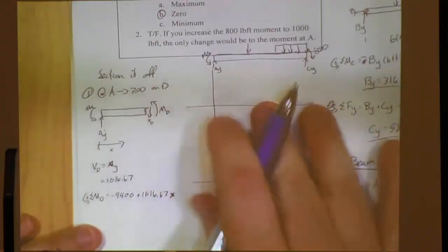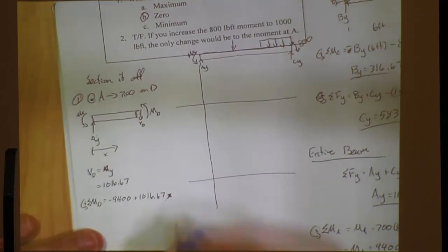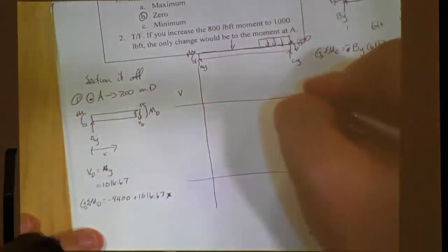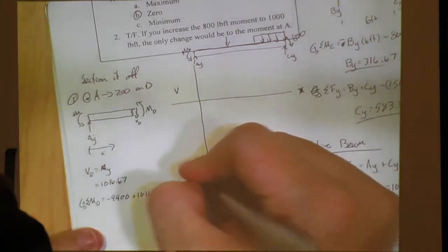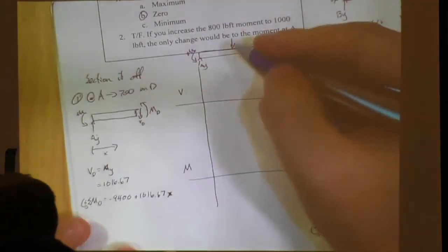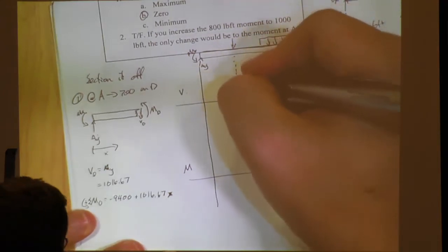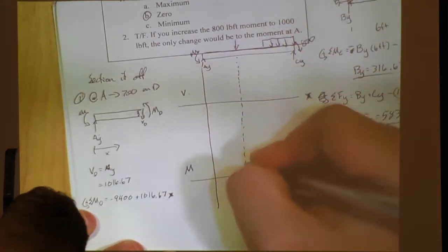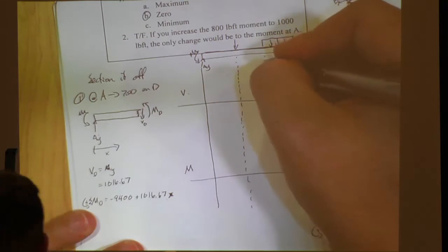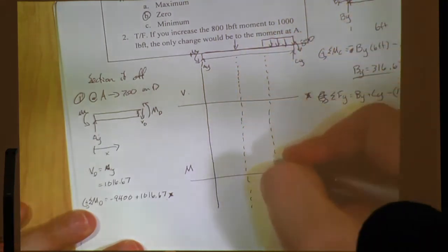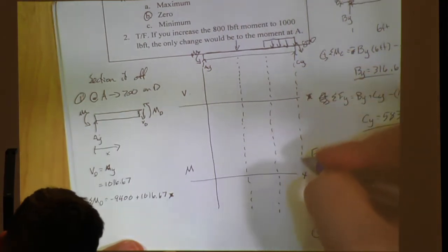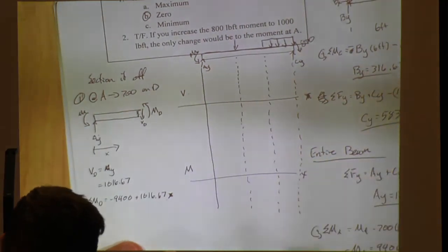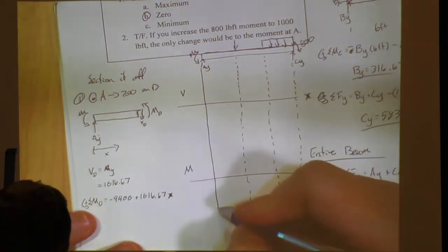Okay, so now, sorry if it's getting in the way. I just want to show you this as I'm doing the equation. Here's our x. So this is our x distance for the shear moment, right? Draw the dotted lines just down wherever you see a reaction or some kind of external force. And does anybody know why?